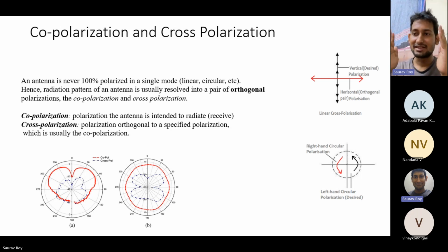So what do we do? Our fabricated antenna we rotate in one plane like this, 360 degrees, and we measure the received value, the S parameters. Then we also move the antenna like this and rotate it again. Why do we do that?